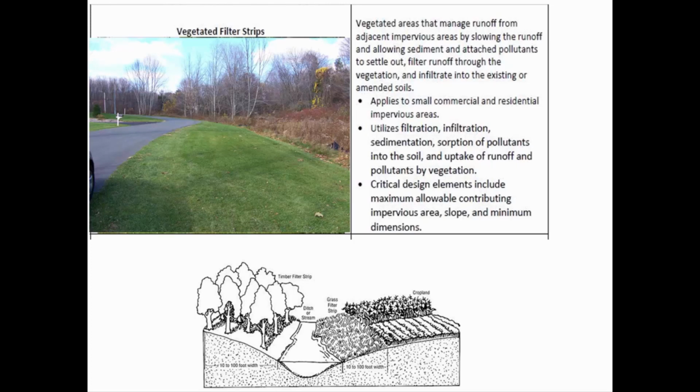So what this best management practice is showing is a vegetated filter strip. So what that is essentially is just a grassy area by the side of the road where water is forced to flow over the surface before it gets into the ditch. They could have put a ditch or a curb immediately adjacent to the roadway, but by doing that, you're immediately channelizing the runoff. Instead, it's better to have a little bit of sheet flow before you go to channelized flow, because channelized flow is fast.